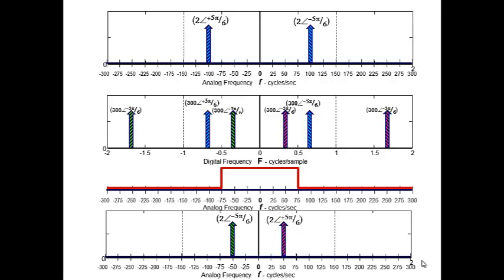Is it practical to sample right at the Nyquist rate? Monsieur Nyquist would say you can do that. And then for the low-pass filter, is it practical to set the cutoff at the Nyquist rate? You can set the cutoff frequency there, you just can't build that filter.